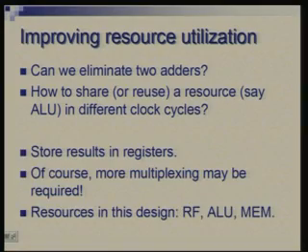Okay. The second issue was improving the resource utilization. Can we eliminate 2 adders? Can we just manage with a single ALU? That is one question. In general, how do we share resources across cycles? Okay. You are using adder in one cycle to do something, in another cycle you can do something else with the same adder. So, the solution lies in having the results of one operation stored at the end of a cycle in some register.